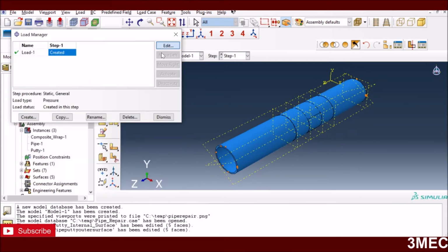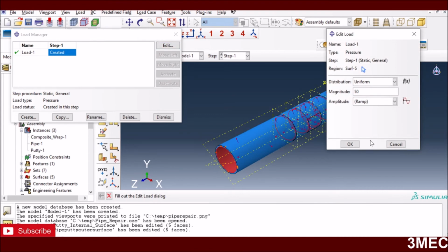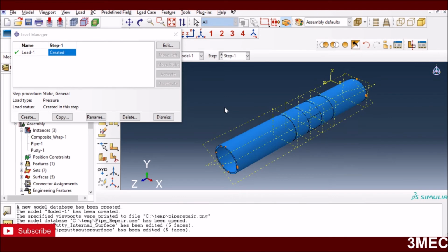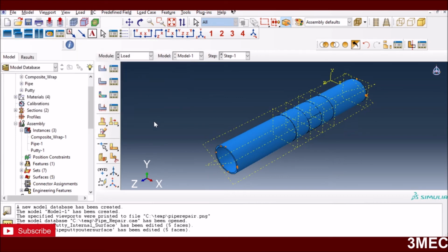Then the pressure load, which is the internal surface load, and you can see I have applied a pressure of 50 megapascals. It's an extreme case, and I want to see at what pressure up to the 50 megapascal it really fails. So again, if you look at ASME section 8, part 4 or 5, I don't remember exactly, but section 8, which deals with FEA, once your elements start to localize strains and your solution starts to diverge, that's the point you take it as a burst pressure or failure pressure in high pressure systems. So according to ASME, that's what I'm going to do here.